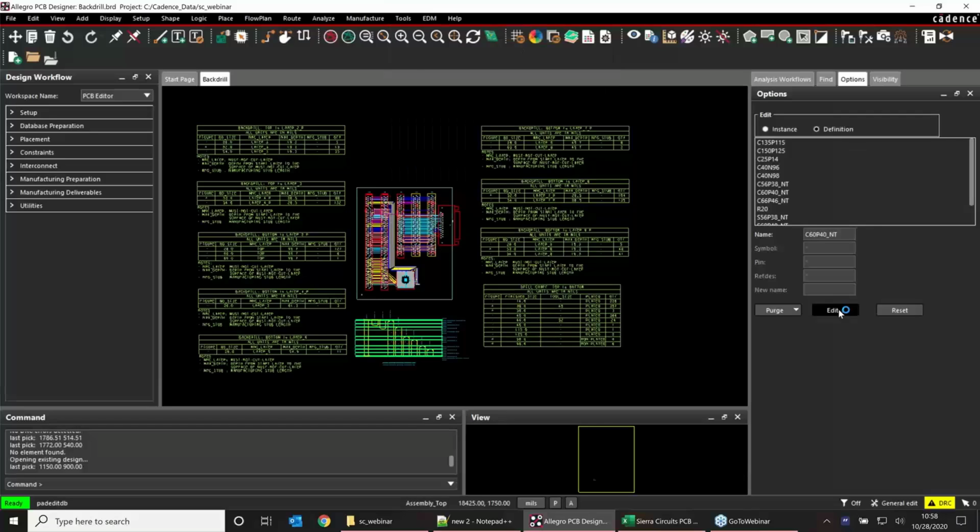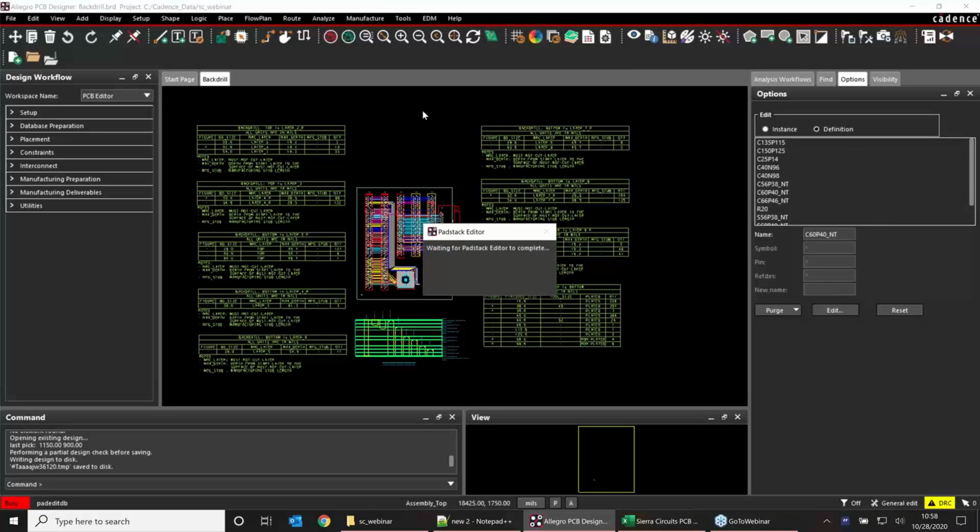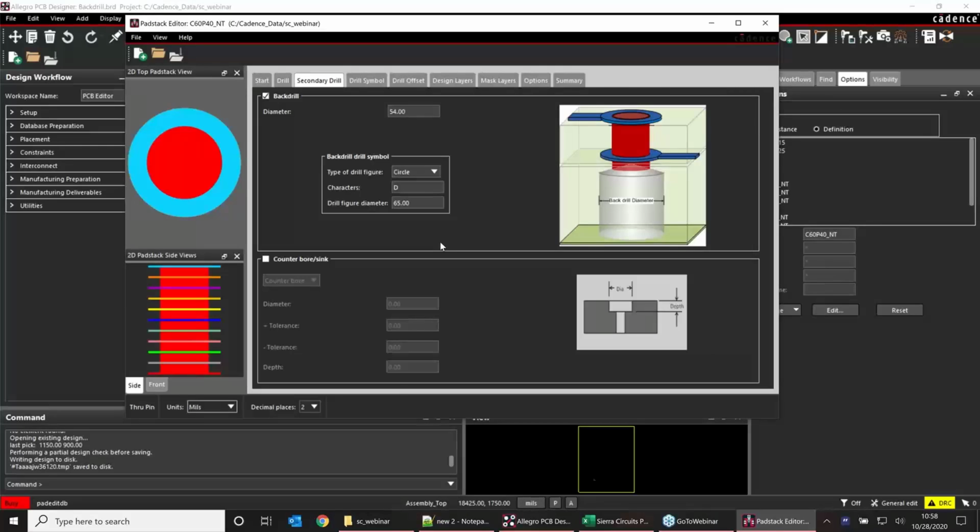So from layer 3 to layer 12, this entire height of the PCB, what you have is a via stub, which will definitely create resonance and some very undesirable effects at very high frequencies. It will attenuate the signals at the resonant frequencies. So the idea is to back drill it and remove the copper from there so that the stub length becomes very small. From a manufacturing standpoint, back drilling has become very mature.